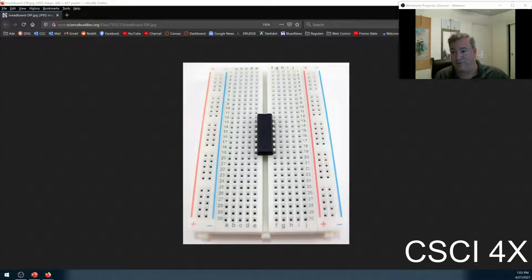Then when the program boots up, because I taught students how to launch a program automatically at boot, it takes a while for Linux to boot because Raspberry Pis run Linux. GNU/Linux, as I'm taking to call it these days. So the fan would sit there spinning and then it would boot and turn off. So I had to teach them about pull-up and pull-down resistors that way. When it's not on, what do you want it to default to? 5 volts or 0 volts? And you have to look up the tech specs for which one is which.